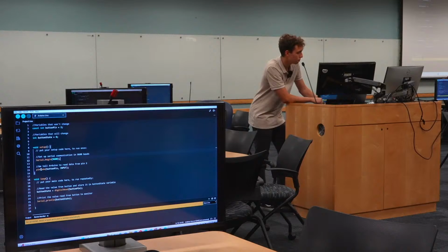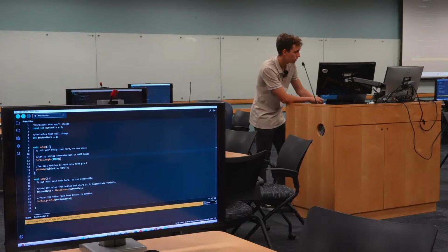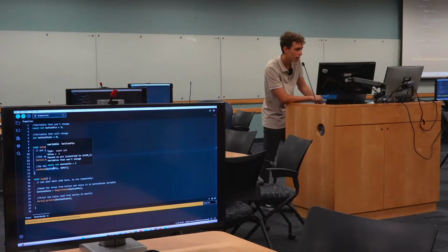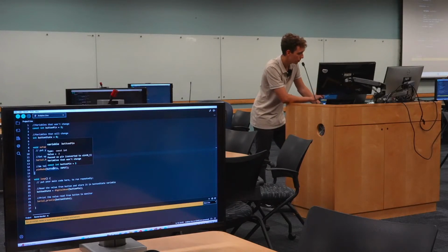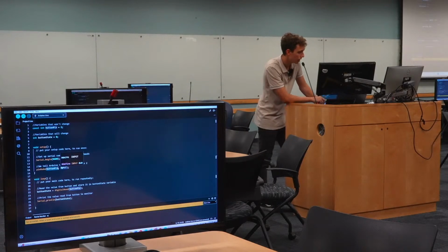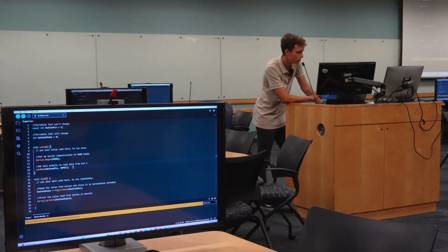And in the void setup here, as you saw in the previous workshop, you're not only going to set up the pin mode. Remember that you use pin mode to tell the Arduino which pins we're going to be using. So in this case, we're going to be using button pin, which takes 2. In the hardware, you see that we connected pin 2, the whole number 2 here. And then we're saying, okay, instead of output, use it as input. So you're telling Arduino in this line, okay, read data from pin number 2, in short.